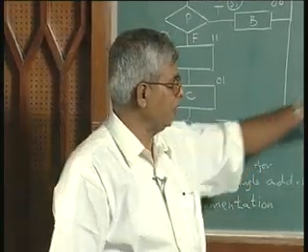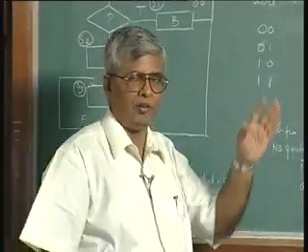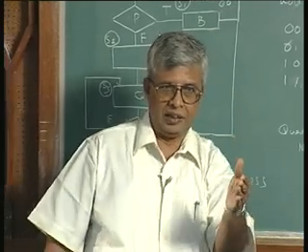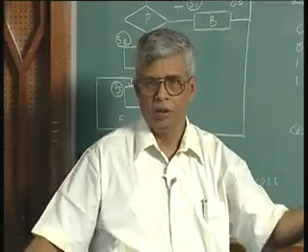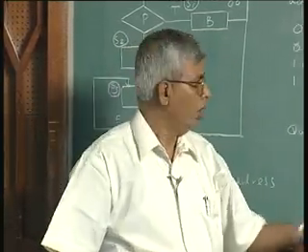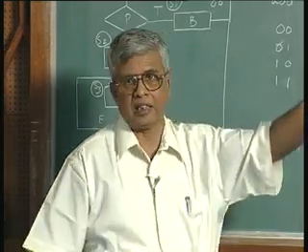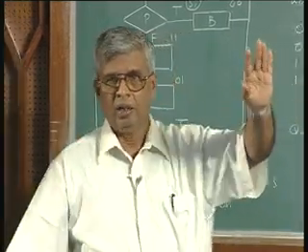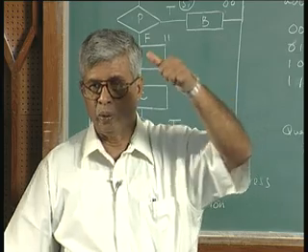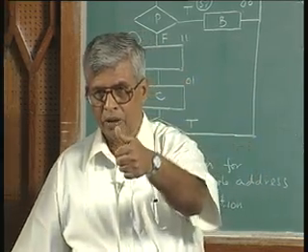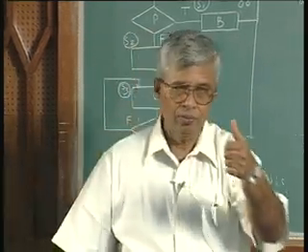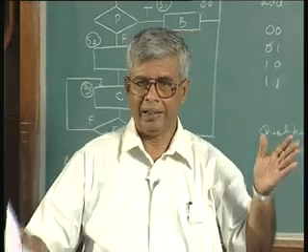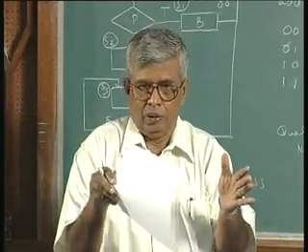Suppose there is no bit added to the qualifier index, supposing the qualifier index was 6 earlier and now it is 7, no problem. And suppose the number of bits for the next address is several bits, then we have saved. Adding 1 extra bit for true false, we will knock off an entire address. To that extent, I can shrink the size of the programmable ROM.